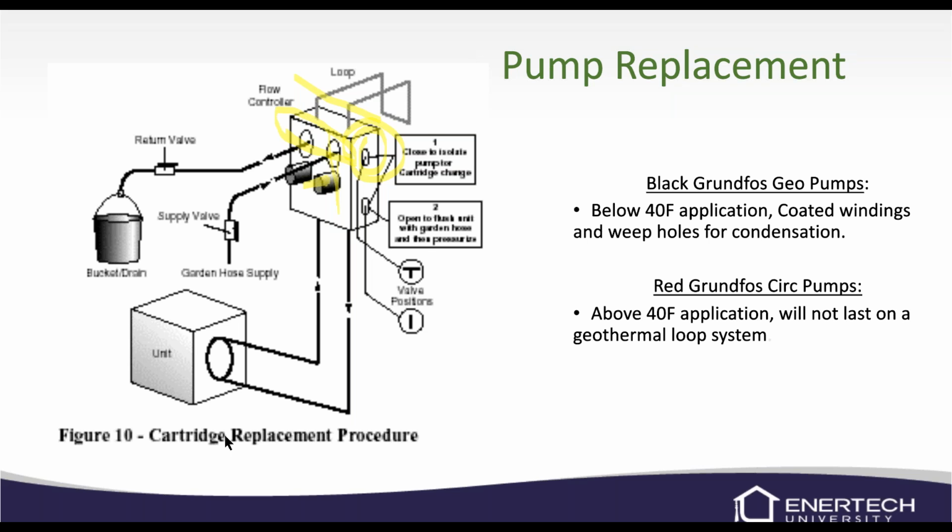If you ever have a flow center that's leaking right on startup, I would always check your connections coming into the flow center. Sometimes if we don't get these pipes coming in straight, they want to kink a little bit or be off center just a little bit. And these are double O-ring fittings, and the double O-ring doesn't want to seal.